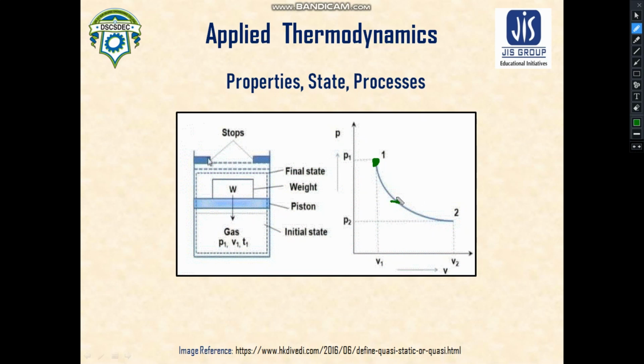Now here, we had seen this graph already. From this diagram we can see this graph has been generated. Now let us assume the thermodynamic process continues. It is what? It is an isobaric process. So it goes up to 3. That means the system is compressed. The volume was larger here and then it got reduced. So it is an isobaric compression process, and the state changes from 2 to 3, and then it goes, sorry, it would be a straight line here, so it goes up to here. So this is an isochoric process.